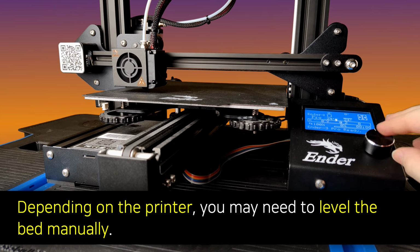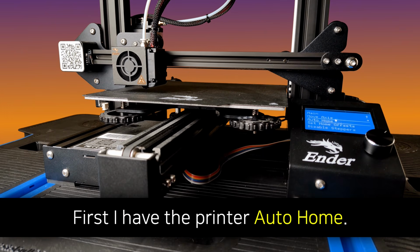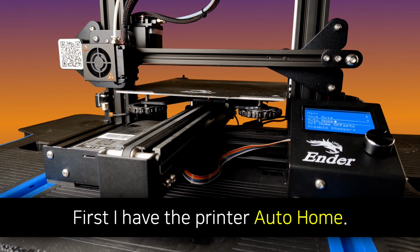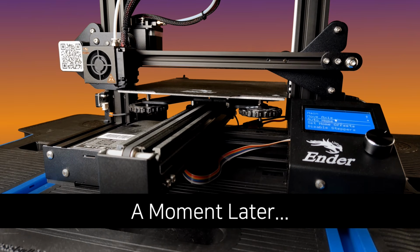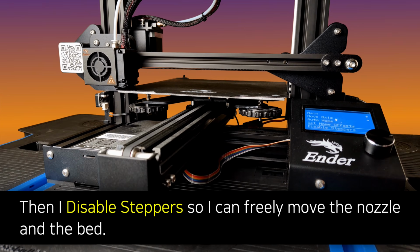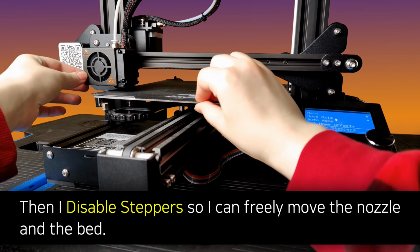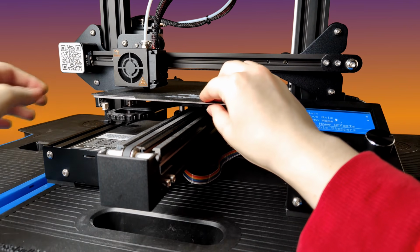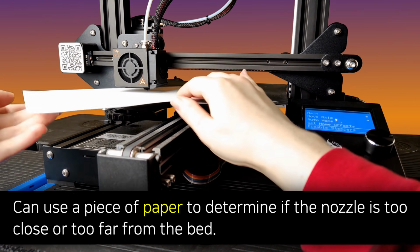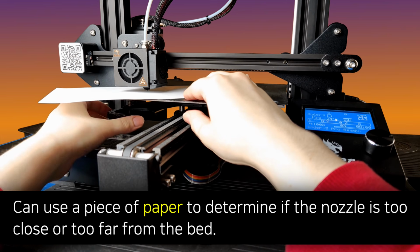So depending on the printer, you may need to level the bed manually. So for my printer, I am first having it auto home so that I can start leveling the printer. After that, I disabled the steppers so that I can move the nozzle and the bed freely without resistance. So in order to level the bed, I need to turn the screws with the gears on the bottom. So near the 4 corners of the printer, I am checking and adjusting the level based on the resistance I